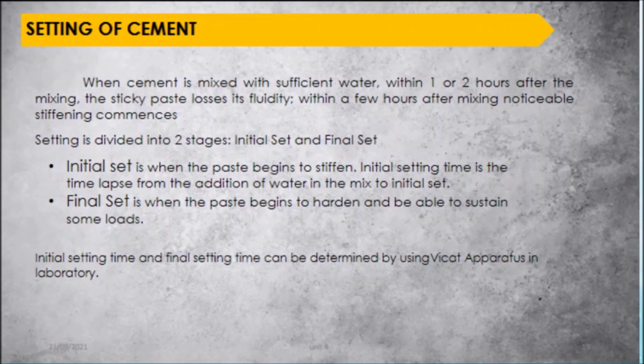Initial setting time is the time lapse from the addition of water in the mix to initial set. Next is the final set. Final set is when the paste begins to harden and is able to sustain some loads. Initial setting time and final setting time can be determined by using the Vicat apparatus in the laboratory.